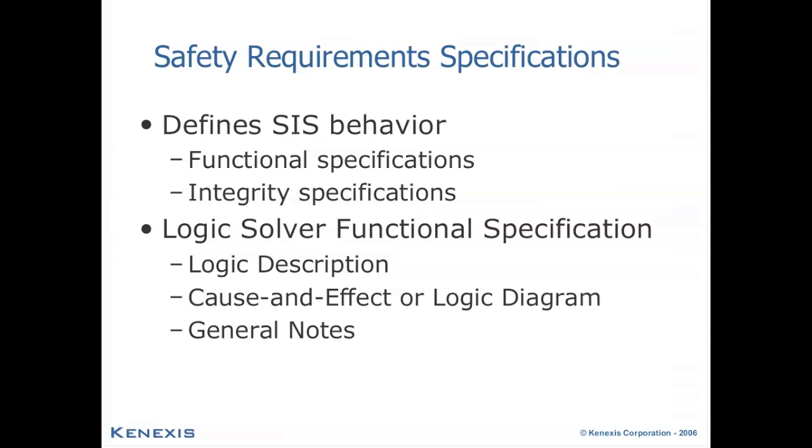If we're unable to achieve our SIL target with a particular design, as determined by these reliability models in SIL verification, then we would modify the design and correct it accordingly to achieve a higher level of SIL and an acceptable nuisance trip rate.